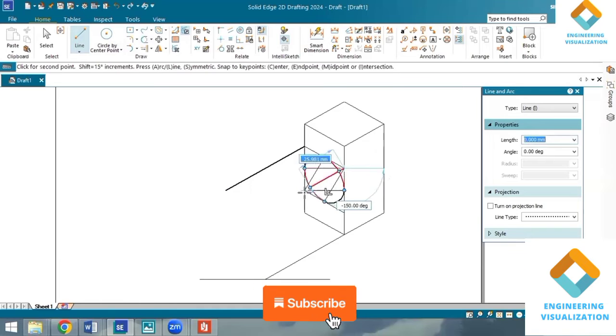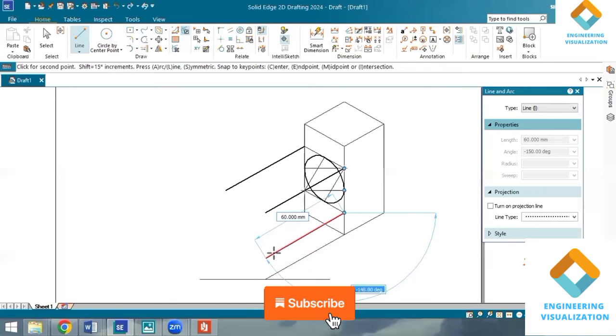Because we should be extruding at a distance of 60 mm, right? That's why I'm considering this length of 60, angle minus 150. From all the four corners of the box I'll be extending the same length, 60 mm, and the angle is minus 150.